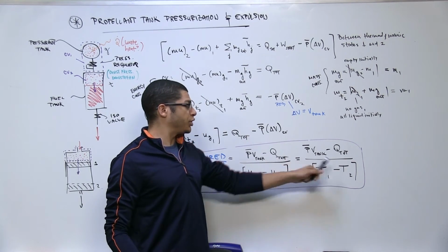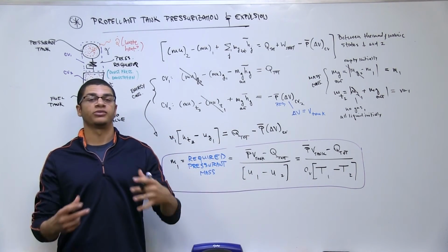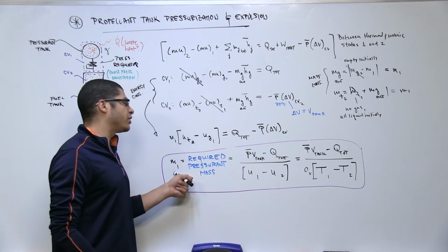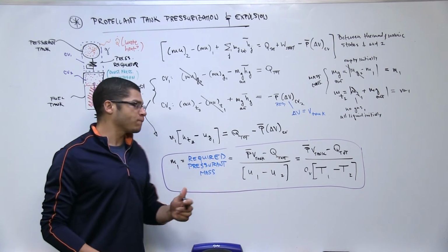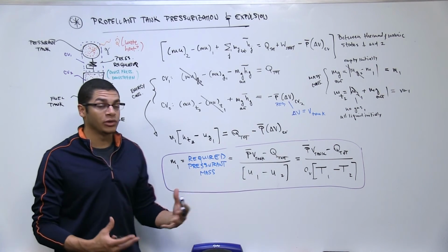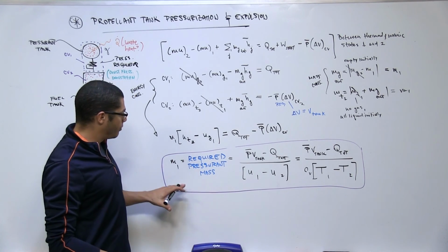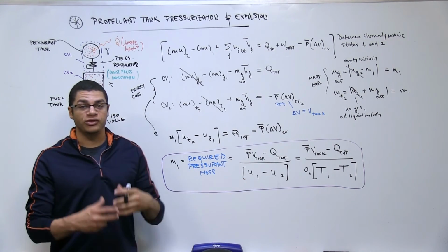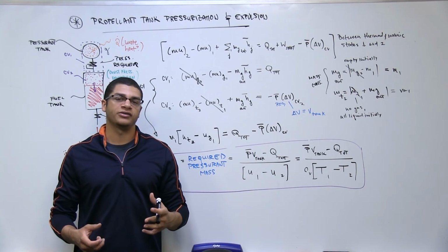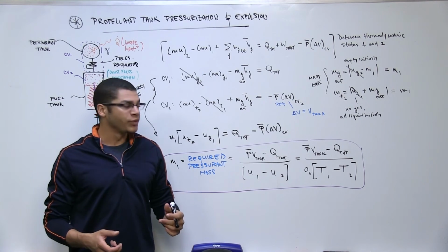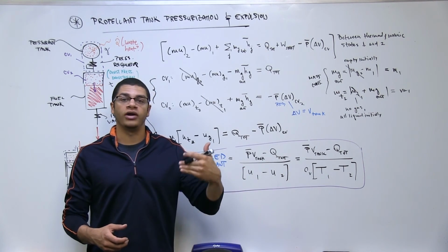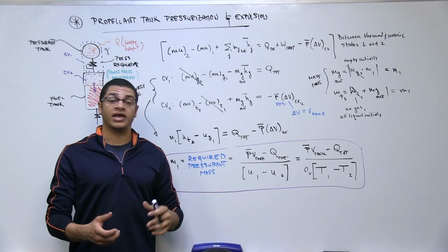Additionally, and I should have mentioned it over here, if there's heat transfer out of the system, so if there's some kind of loss of energy, that is going to increase our demand for pressurant, moving in actually the opposite direction. We would like to minimize this. So again, recapping, there's a lot of information in this equation here, from just a simple energy conservation analysis for a pretty practical problem. And if you get a chance, you can go back and incorporate a few more details into this to get even more insight.